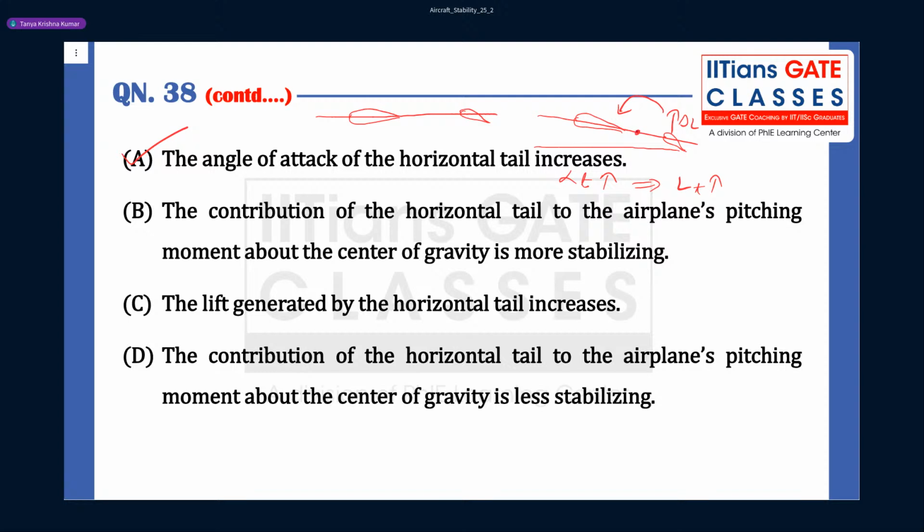Okay, nose down moment. So it is producing a restoring moment as opposed to the disturbance. So the contribution of horizontal tail towards pitching moment is stabilizing. Now we need to remember here that this lift will increase until stall is what we have learned. But since we are neglecting the stall effects, there is no such limitation on our assumption.